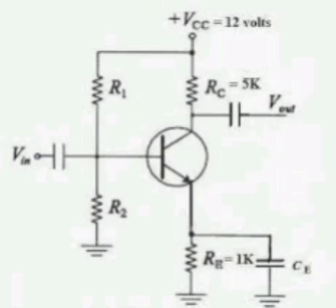Next question is, design an amplifier that has a voltage gain of 2 if Vin is less than 0 and 1 if Vin is greater than 0. Assume ideal diodes and ideal op amps are available. If Vin less than 0, then V0 equal to Vin. If Vin greater than 0, then V0 equal to 2 Vin. Such circuits can be designed by using a precision half-wave rectifier, a unity gain inverting amplifier, and an inverting summing amplifier. These are the three circuits that can be drawn.